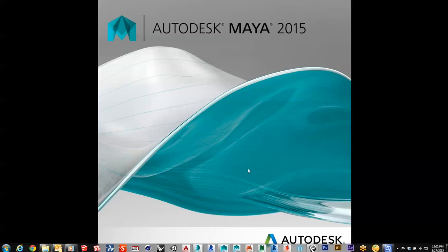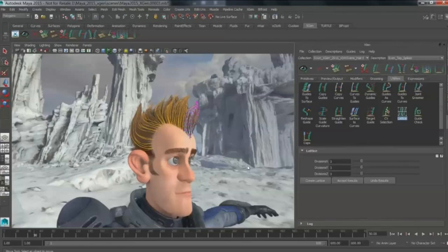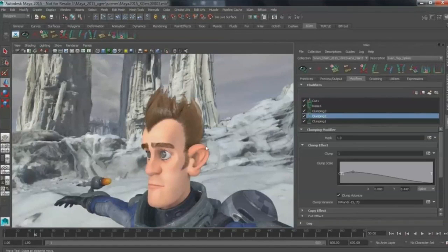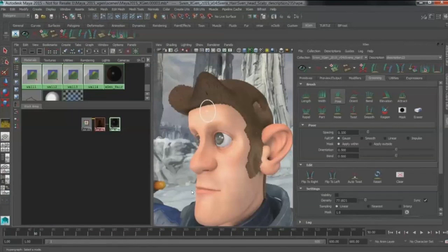We also have fun new differences in the Maya 2015 and upgrades. The XGen arbitrary primitive generator is useful for hair creation and also for landscape placement. So if you want to throw around trees and bushes, you can scatter those with a lot more ease. In this situation, we've changed a few modifiers to improve the quality of our character's hair, and then thrown in a new texture right on top of that.